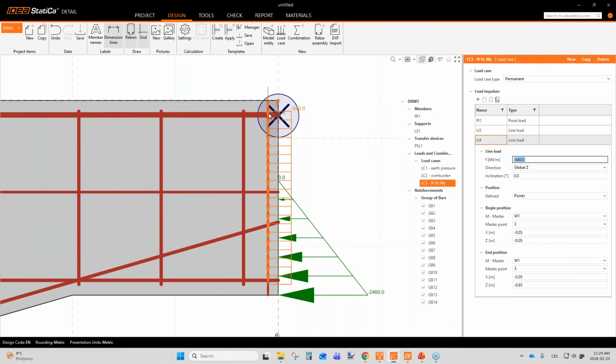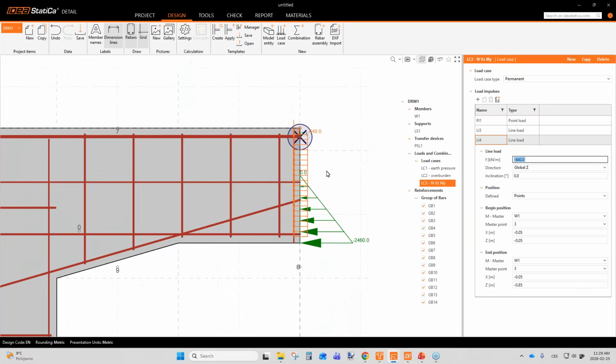Like that. Okay, so we don't have this vertical shear load acting on the edge of the frame joint, but a little bit into the structure, so it can be better transferred during the numerical calculation. So this way we input this set of internal forces into this frame edge.